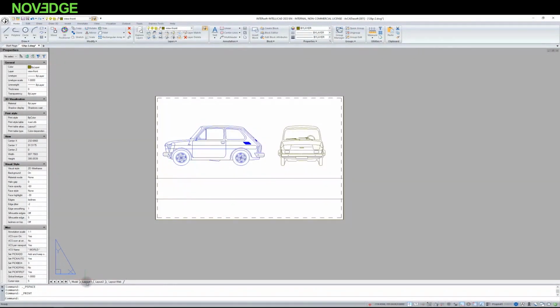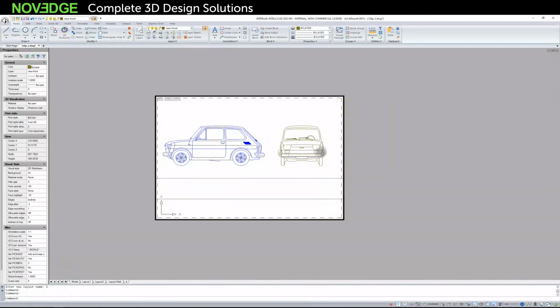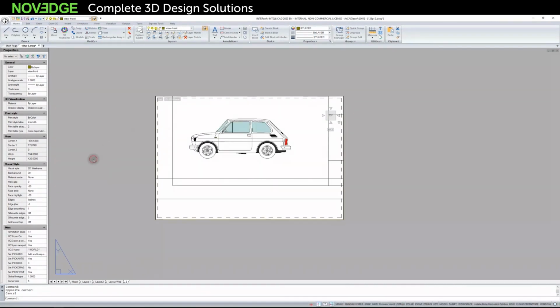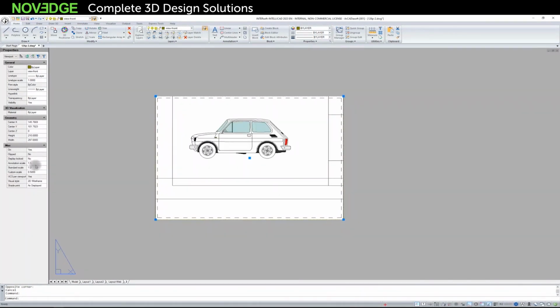If we have such a defined sheet, we can duplicate it. We'll make 2 copies. And why? Among other things, so that we can just change the drawing number and the drawing name and so forth. On this drawing, we only do the following. We move to a different range from our model, disable sheets from our model, and have a predefined sheet without the need to set it up again, without the need to redefine it.